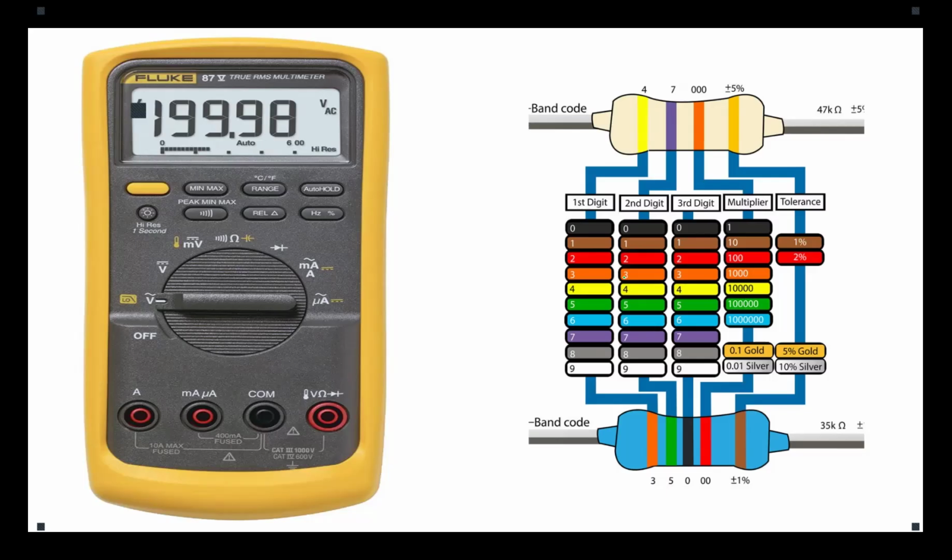Let's talk about the lab. What is going to happen in our lab when we want to read a resistor using measurement? You have your ohm meter or digital multimeter. When you want to read the resistance, first of all, the connection of the probes should be parallel. So your digital meter should be parallel to your resistor in order to read ohms.